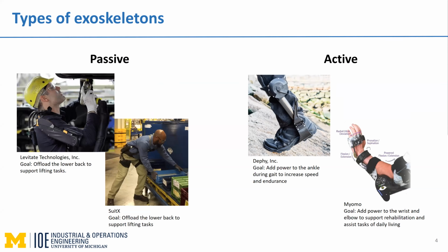Different use cases will have activities that consist of a variety of tasks, and it's important that the exoskeletons be evaluated for the relevant task-specific postures. When determining the necessary adjustability of an exoskeleton, it's important to consider a multivariate approach to anthropometric dimensions, where you evaluate different combinations of the underlying anthropometric measures. People all have different shapes and sizes, and this can influence what workers may fit into a particular device. There's also a subjectiveness to comfort, which can lead to a different desired static fit across users.